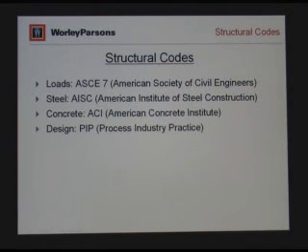We're currently going through a real interesting evolution. The senior experienced fellows like myself have been used to using allowable stress design, where basically we compare the stress in a particular member with the yield strength divided by a factor of safety, which gives us a so-called allowable stress, as opposed to, like concrete, ultimate or strength design or load factor design that we're currently using. There we compare the demand on a structure, with load factors for dead load and live load, with the yield or the capacity of the member.